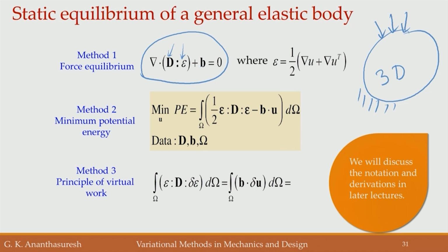If you were to take a differentially small element, a little cube here, I am drawing a very big cube here, but imagine this cube to be as small as one can imagine, and then look at the various forces that act. What are the forces? External forces B that act on it, and then you have stresses multiplied by the corresponding areas, normal and shear stress, and what total force will be there. Likewise, on all the 6 faces of the cube, when you balance it out, you get this vector equation.